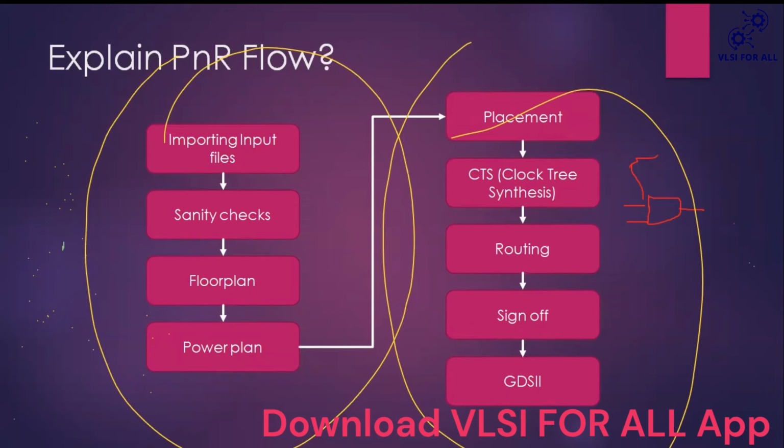So the middle of the core area will get an early clock if the clock port is at the bottom left of the core area, because the distance between the clock port and the standard cell is very less compared to the other flip flop.